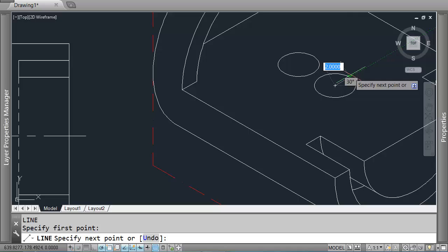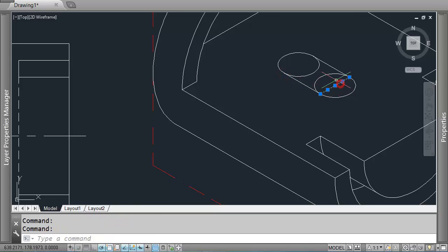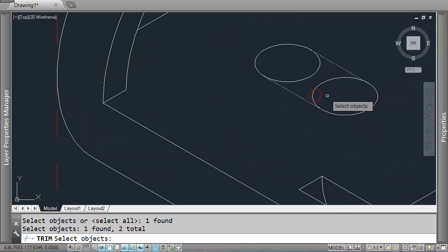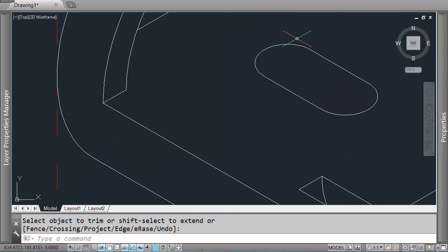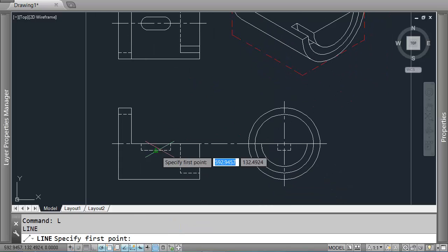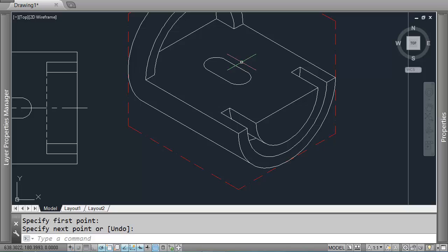Now I need to take away every part of this shape except the parts which are describing this kind of outer edge. So I'm going to use trim on these lines and take that away. So it's not just a line which is drawn on top. This object has some depth. If I check my front view, I can see the depth of the shape is 2 units.